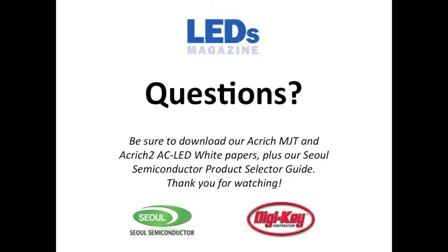You talked about AC LED a little bit, and maybe there's a little confusion between what an AC LED is and what a high voltage LED is, or even what an AC LED was a couple of years ago versus now. Because I know you talked about what was called anti-parallel. You have a string of LEDs in each direction, so you get them working on half waves of the AC mains.